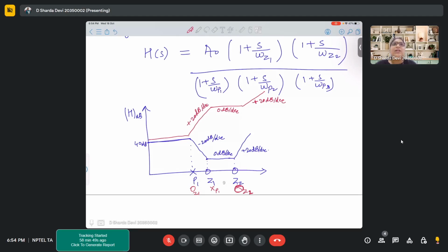So what we say is, for an op-amp, it will need a power supply, right? You cannot turn VDD off, that power supply cannot be turned off. But let's say the input signals or input supplies can be turned off. Only one source will be there, and that particular source is the test source that we are applying at the output.